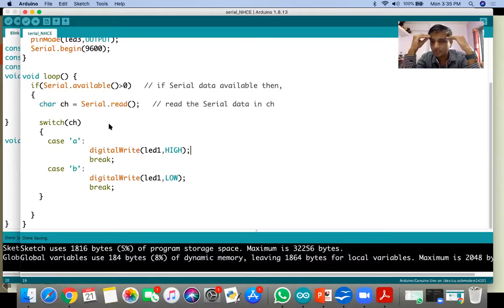So, Bluetooth-enabled sensors or Zigbee, Wi-Fi? Yes, yes, yes. All Zigbee can also be interfaced. Bluetooth can also be interfaced. Any wireless sensor can be interfaced if it is serial. Actually, it is serial only. Zigbee is also serial, Wi-Fi is also serial, Bluetooth is also serial. Bluetooth HC05, HC05 is the Bluetooth sensor. Zigbee sensor is already there, and the Wi-Fi is ESP01, which gives the serial output.